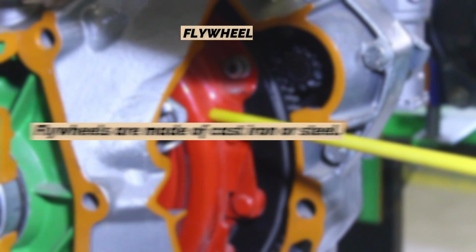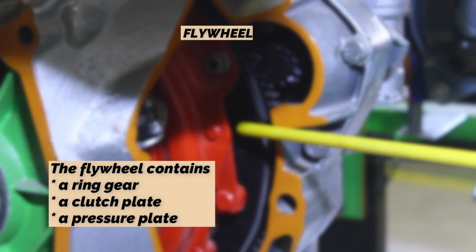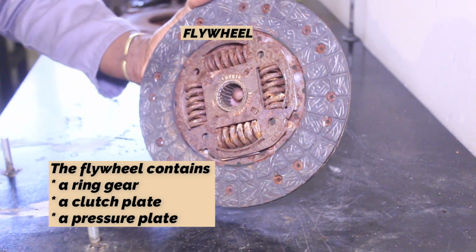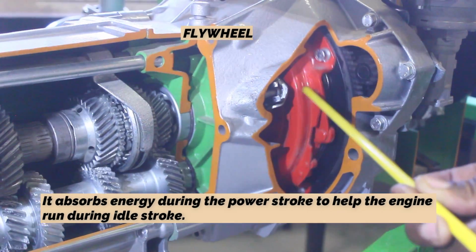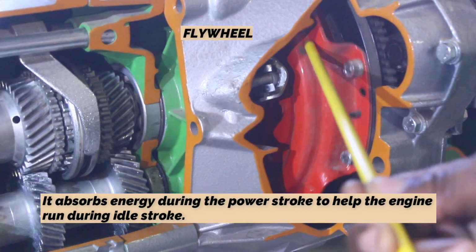Flywheel. Flywheels are made of cast iron or steel. The flywheel contains 1. a ring gear, 2. a clutch plate, 3. a pressure plate. It absorbs energy during the power stroke to help the engine run during the idle stroke.